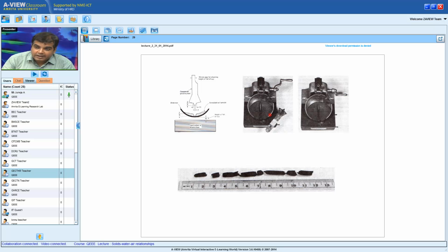However, the Indian standard, because we like to please both the people, says you can use either of the two tools depending upon how much plasticity or stickiness there is in your soil. So please refer to the IS code for the relevant tool. Let me come back.